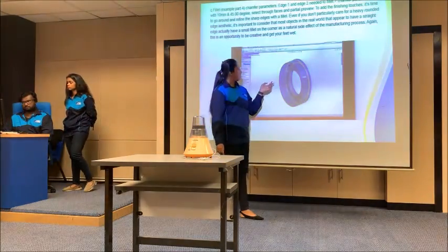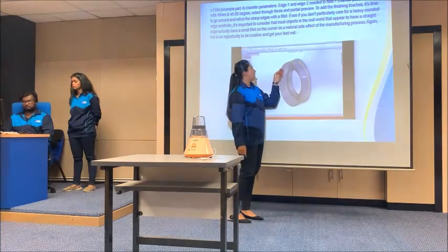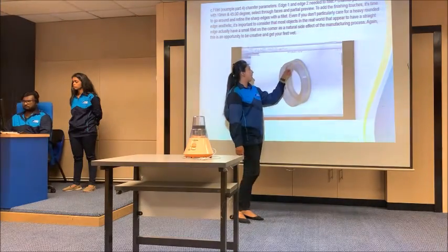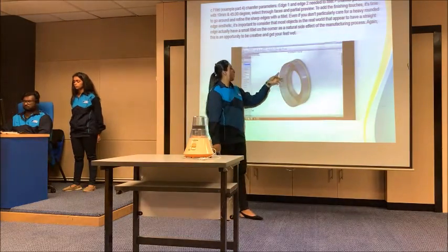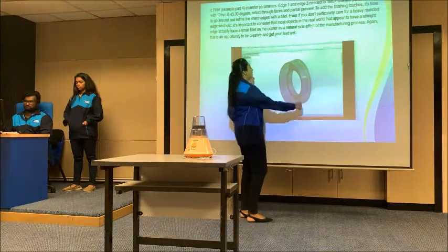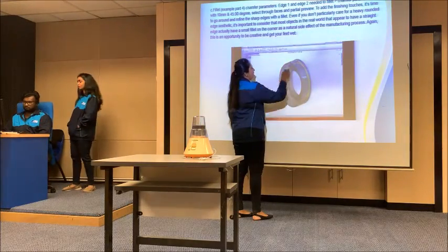We done with a circle, and then we dimension it, and then give a through hole, give an extrude base first, and then we through hole and extrude cut this particular part, and now we needed to give some fillet over this edge.